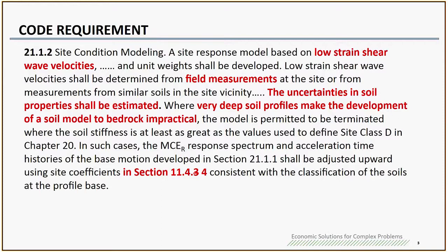In the previous class, I talked about the input motion should be developed at the bedrock. So if you cannot drill to the bedrock, basically you can scale your spectrum up to either the site class D or site class C spectrum, then use that as the target spectrum for input motion. Then you use that input motion for site response analysis.